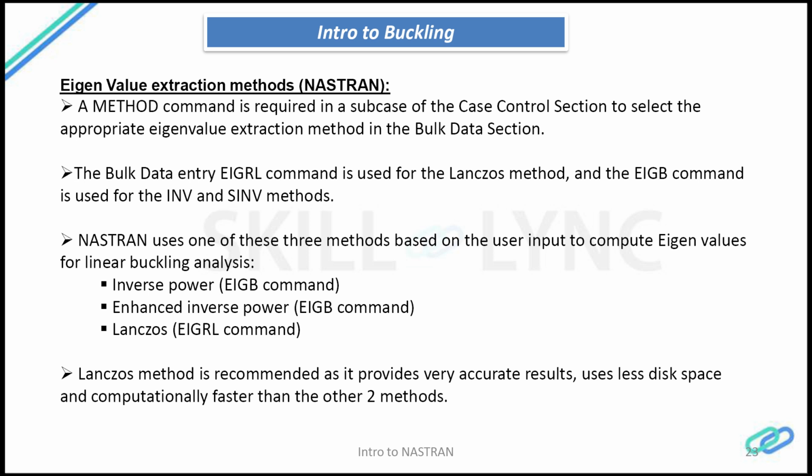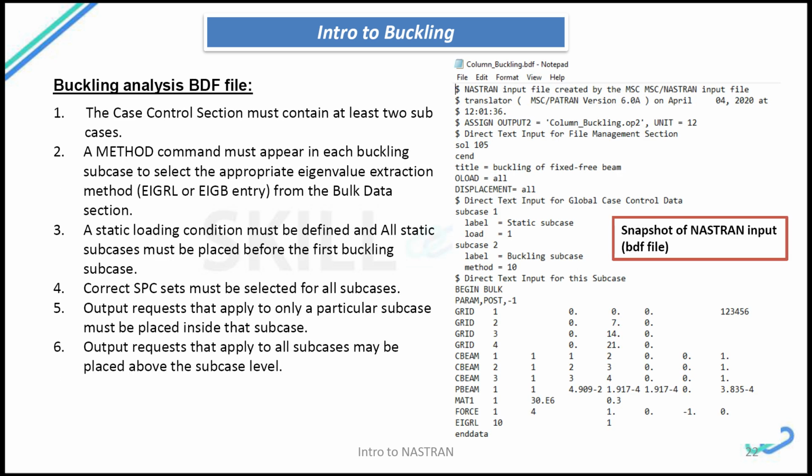Now a little bit in detail on the eigenvalue extraction methods. As we have seen, a METHOD command is required for any buckling subcase, so that it redirects while solving the problem. It uses that particular command, and we have to specify how many modes we want to extract from the buckling problem and those kinds of things in this command, and that will be taken into account.